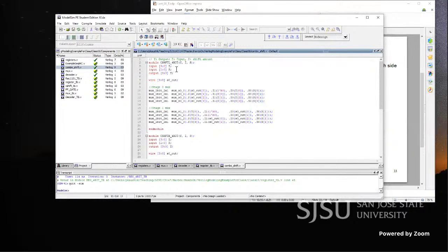So what I was telling is that since my shift is bound by 0 to 3, we cannot go beyond a 3-bit shift because it will anyway result in 0 if we go beyond that. So we restrict our shift amount to be 2 bits, with an input of 4 bits and output of 4 bits. Now, the connection details are this. If my shift amount at that stage is 0, meaning no shift, then we just follow through the input. Otherwise, we do some shifting.